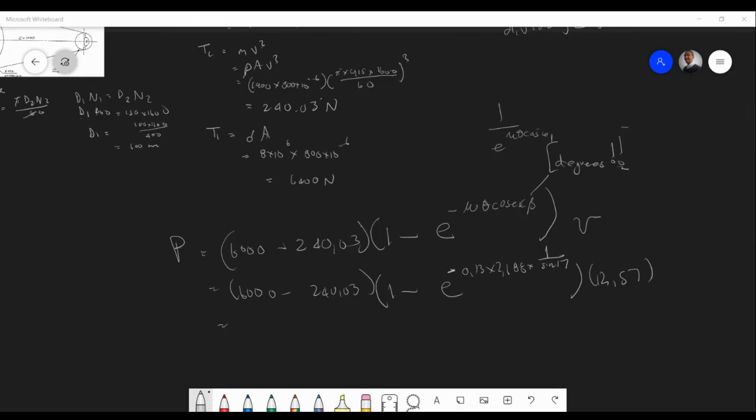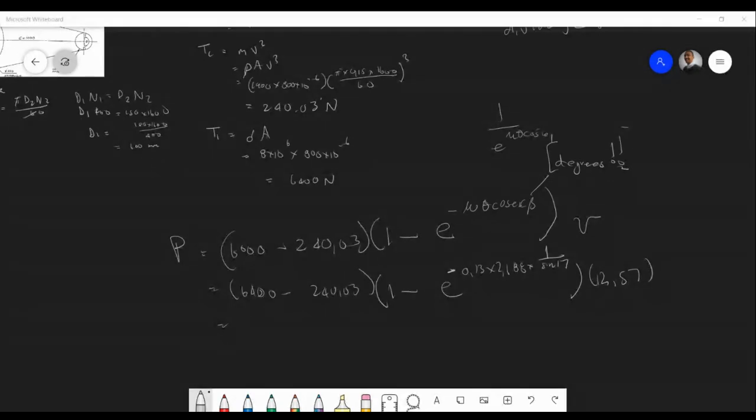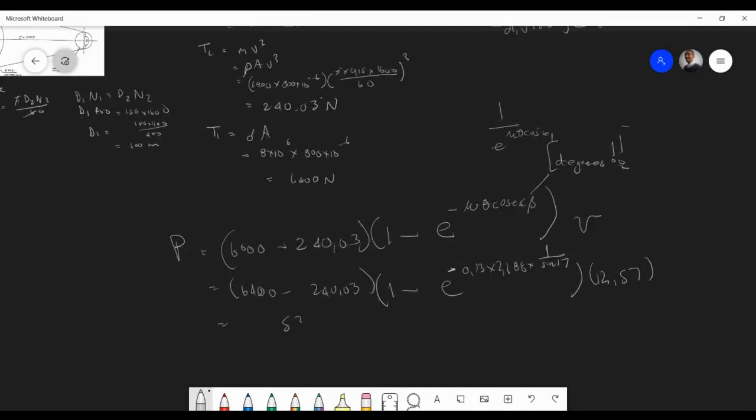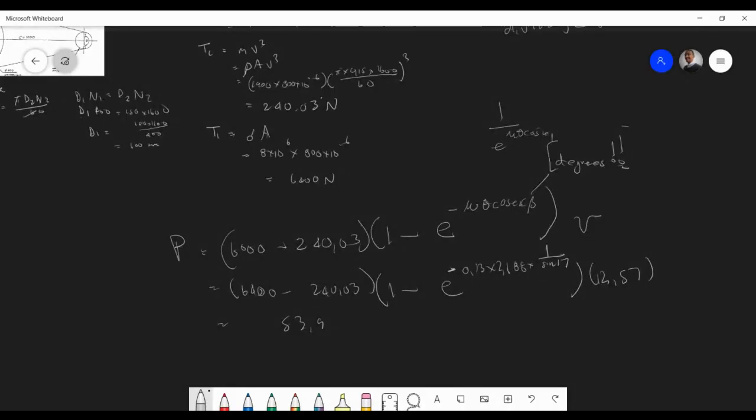Oh, that's 6,400 here. That's the first thing. It's still awfully high though. What is the centrifugal tension, is it 107? Yeah, 53 should be 53,996. Thank you, Tommy. That looks right here. Around 50, let's call it 54 kilowatts. Yeah, that looks good. It's a lot of power being transmitted there.